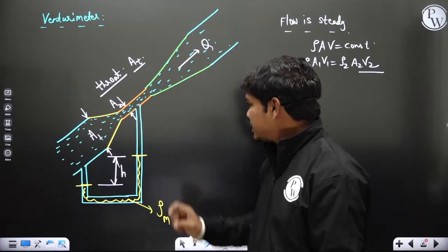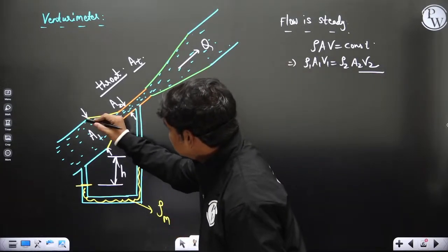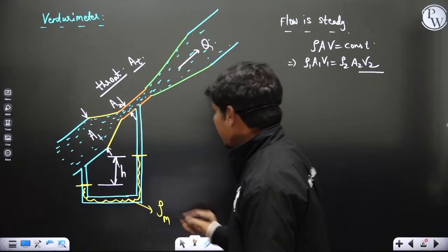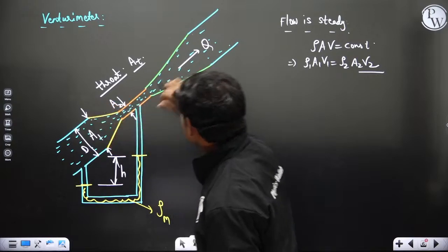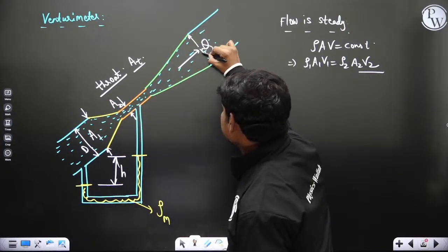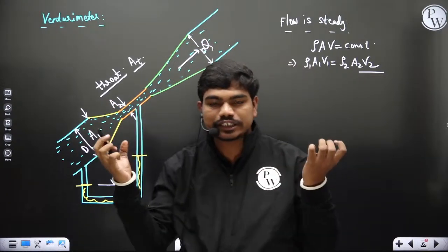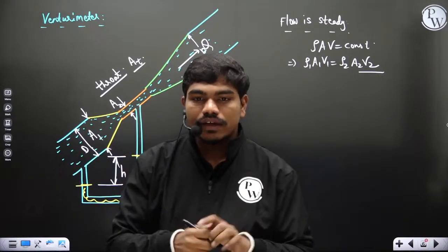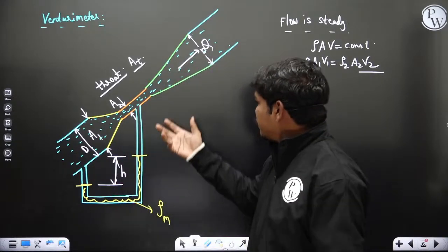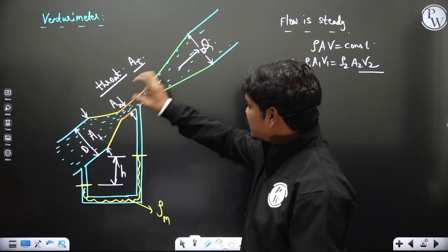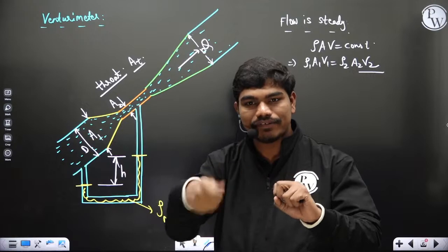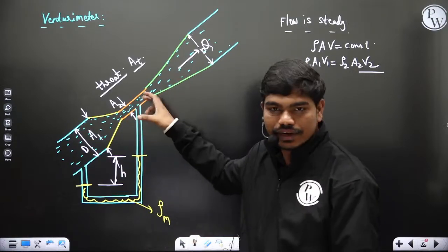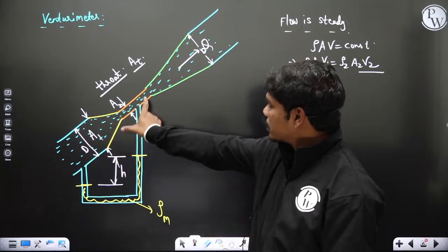flow rate? First thing is the diameter here, which is basically this opening, and the diameter here, they'll be the same, correct? Because it should be adjusted to the same pipeline. Now, in many cases, or in all cases, you cannot connect this nozzle in the reverse direction, okay? Even though mechanically you can fit it using flanges, from a fluid mechanics point of view, you cannot do it in this way.